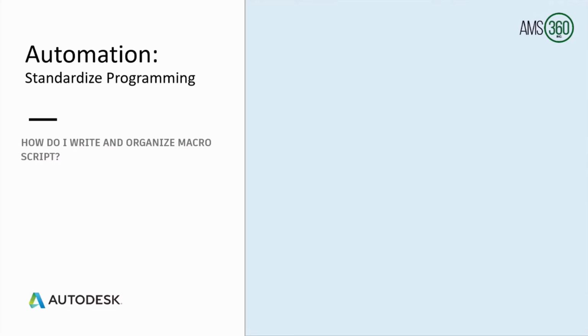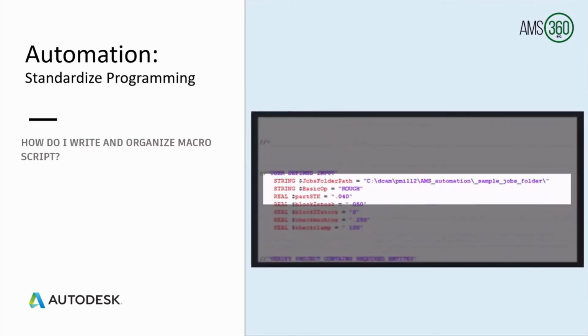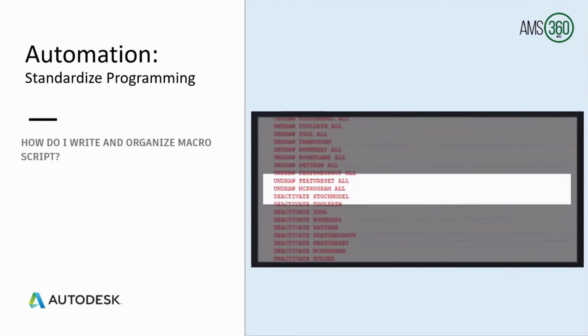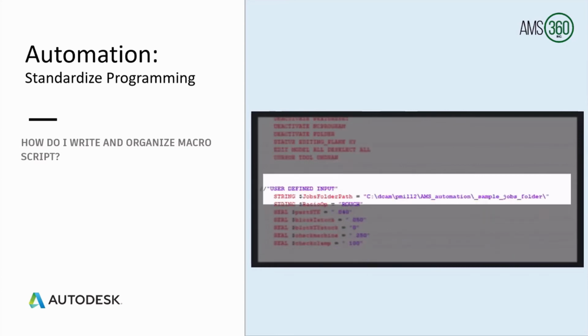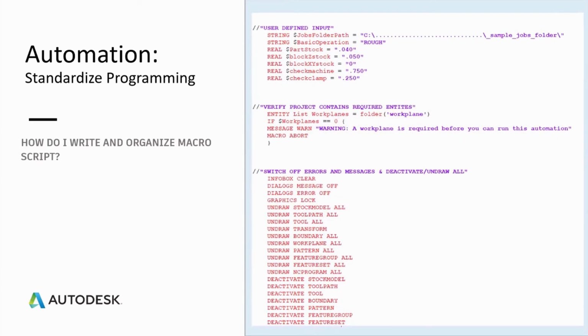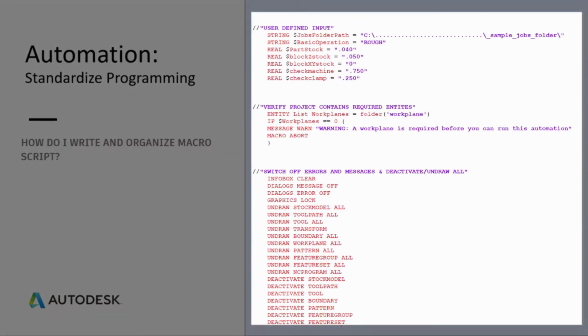Returning to our tips and tricks on macros, let us look at the actual macro text. This looping clip offers a visualization of how the code is read line by line. Now, looking at this still snapshot, take a moment to appreciate the friendliness of this layout. This is my first suggestion for all of your macros. Take the extra bit of time to label each group of lines, and cluster these lines as relatively small groups if possible, that perform manageable sections of the puzzle.